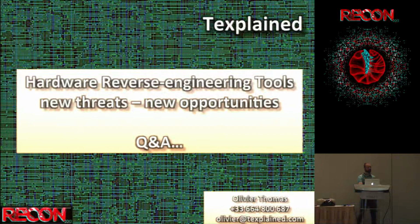Then, if you want to have also the capacity to perform the invasive attack yourself, you have to buy a FIB and a probing station. It starts to be really expensive because if you want a FIB on the second-hand market, and you want a nice FIB because you want to do backside, because maybe you will have PUF sometime or things like this, it's $500,000.